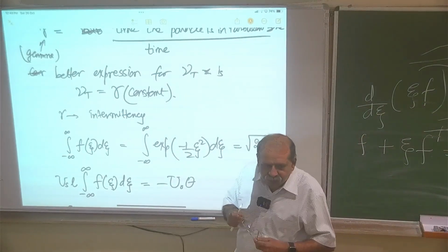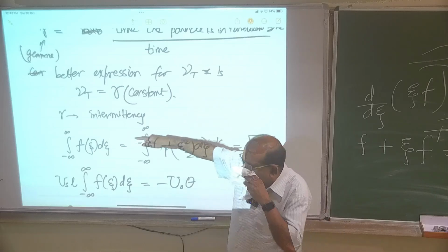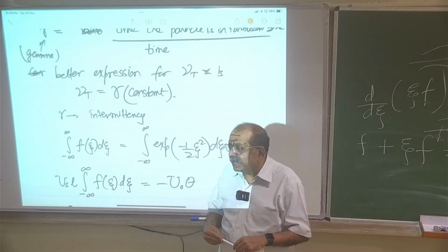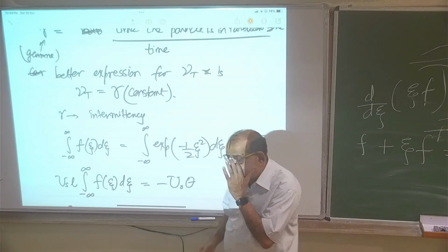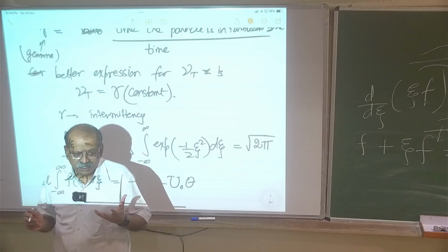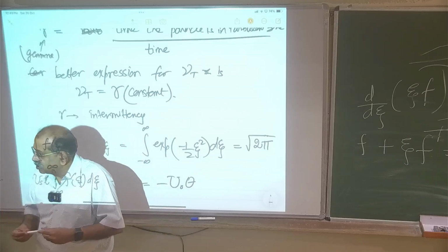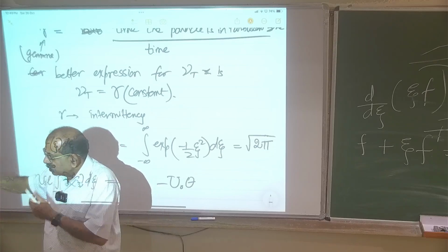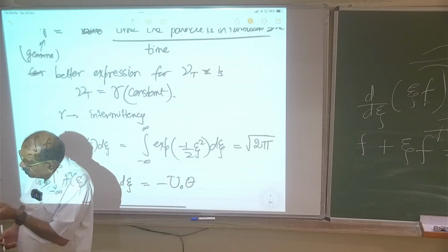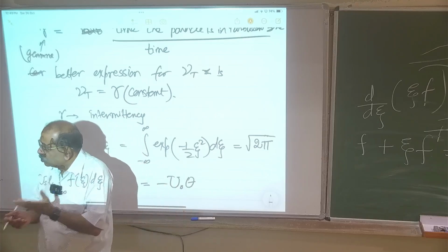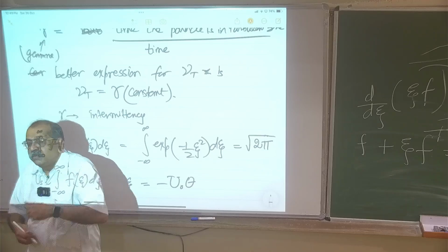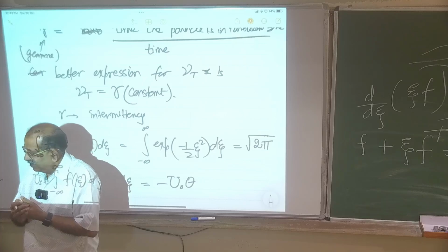What we now have is a form for the Reynolds stress and for the mean velocity. Next we look at the turbulent kinetic energy budget and try to see how the different terms vary with zeta. There's a production term, there's an advection term. At many places to make those estimates we will use this form of the profile, but we'll also have to use some empirical data.